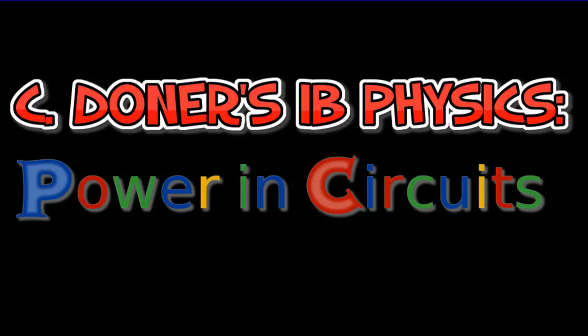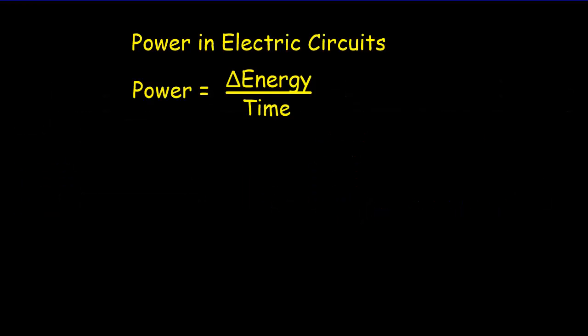Let's have a look at power in electric circuits. So we know that power is the change in energy, or the work, per unit time. And when we were looking at electric potential, we came up with a little equation that the work, or the change in energy, is equal to Q times delta V. So we can replace that change in energy by Q delta V and put it over time.